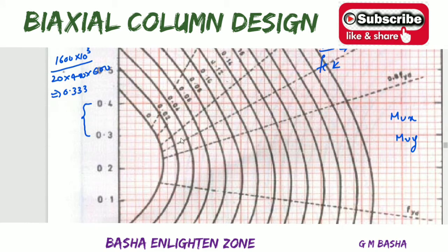This is the curve related to 0, and this is 0.02, 0.04, 0.06. Your p by fck value is 0.052, so the curve will be taken somewhere in between 0.04 and 0.06.